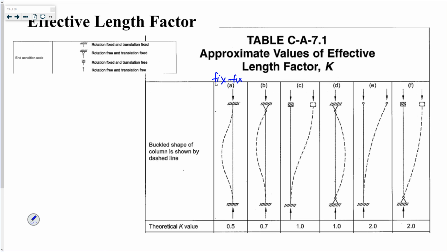And you can see there's your pin buckled shape, 0.5 times your L. If you look at B, pin on top and fixed on the bottom, there's a point of inflection right here.